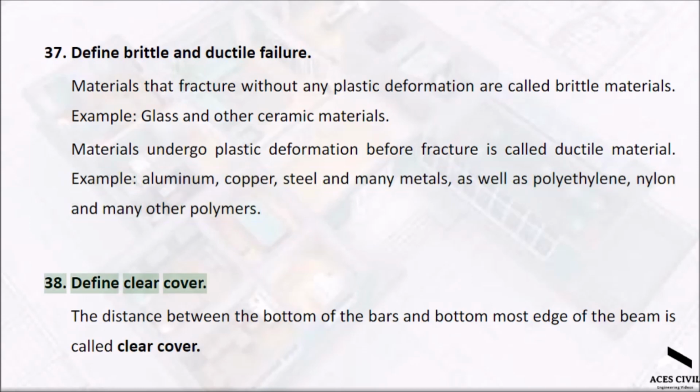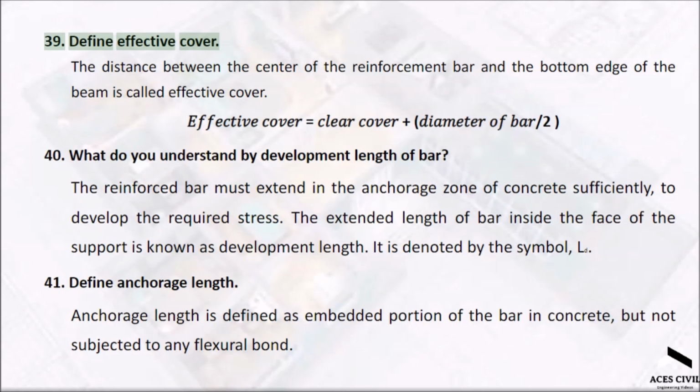Define clear cover. The distance between the bottom of the bars and the bottommost edge of the beam is called clear cover. Define effective cover. The distance between the center of the reinforcement bar and the bottom edge of the beam is called effective cover.